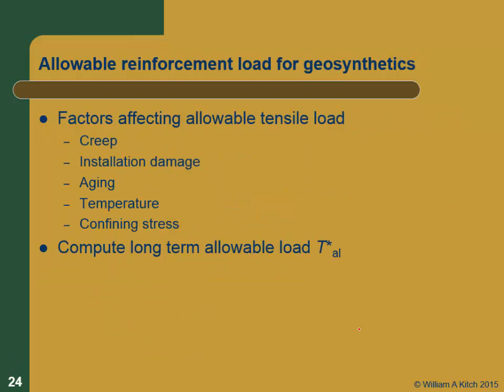All right, so let's talk about allowable reinforcement for geosynthetics. Completely different world. A lot more things going on with geosynthetics. Geosynthetics have a tremendous creep problem. If you put loads anywhere near their actual rupture loads, they're going to creep forever, and your wall is going to be moved out into the roadway long before it fails. So creep is a big issue.